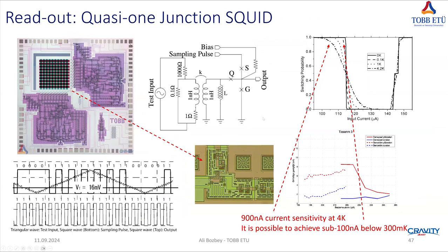And for the readout, we need to just see the frequency. We don't need to measure the amplitude of the qubit signal if it's at 7 gigahertz or say 8 gigahertz, at 0 state or 1 state. So a simple comparator circuit with 1 bit or few bits resolution will satisfy it. And then the output currents are in the order of 100 nano or below 100 nano.